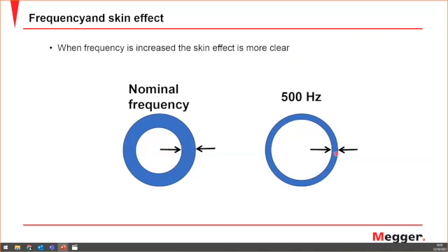At higher frequency, it will be less. And this will cause even more and more loss when you start having issues like shorted strands within the lamination, within the core, in both regions. So this is a good test, a frequency response of stray losses, to detect this.